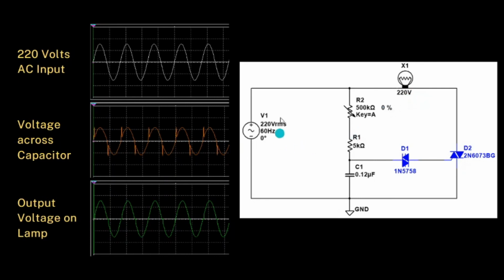So again, this particular circuit we can apply whether it's light dimming, temperature control, or heat control, and lastly speed control for our motors. Okay, and we are utilizing here two bidirectional devices, the DIAC, which triggers our TRIAC, and a charging circuit. That ends our discussion for this session.